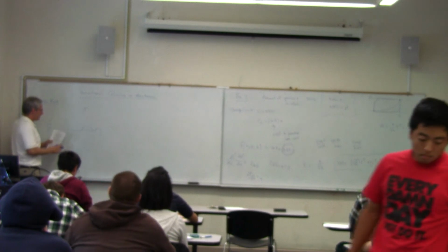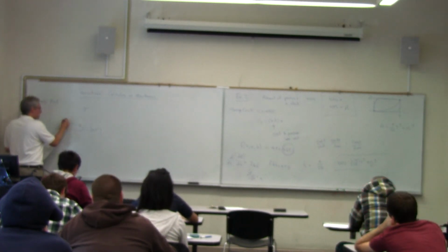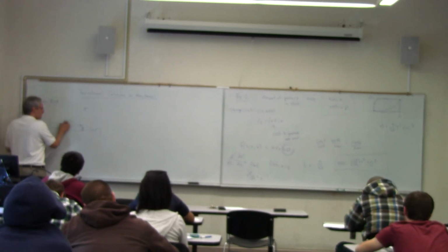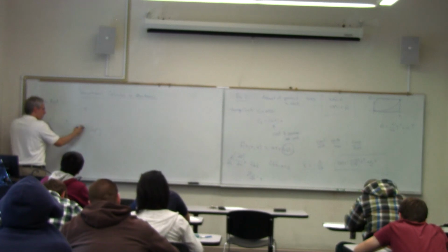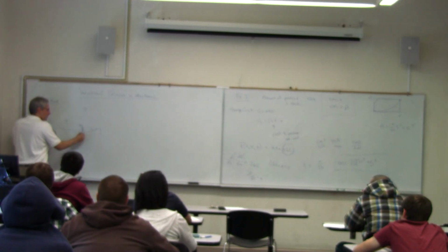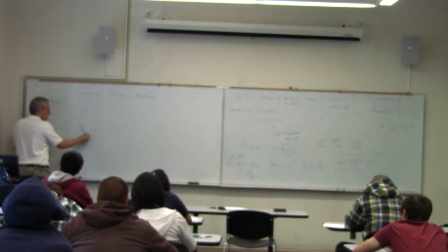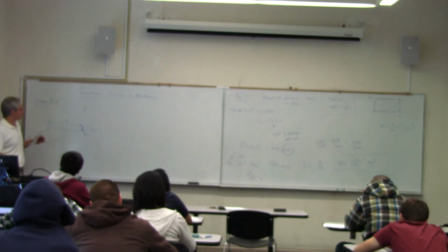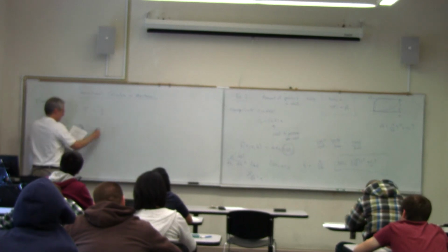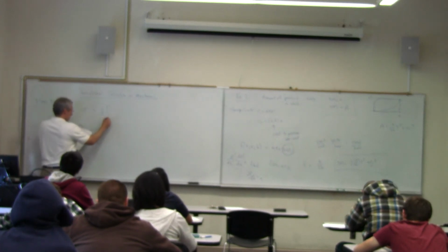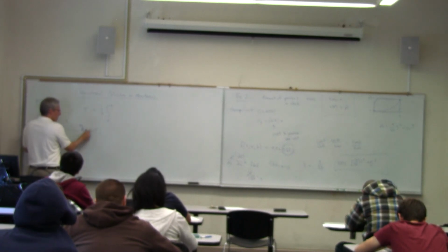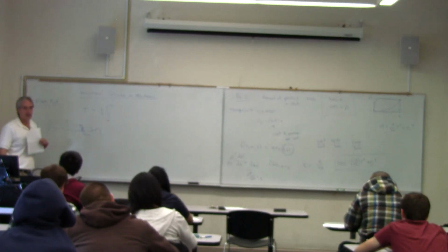And it turns out that, so if we say that the position of a little slice here before any deformation is x, and then if this rod deforms a little bit so that this little sliver moves by a little amount u of x at time t, then we can write down the kinetic and potential energy for this rod. The kinetic energy is going to be 1/2 the integral over the length. So we're going to add up the kinetic energies of an infinite number of infinitesimal slices.